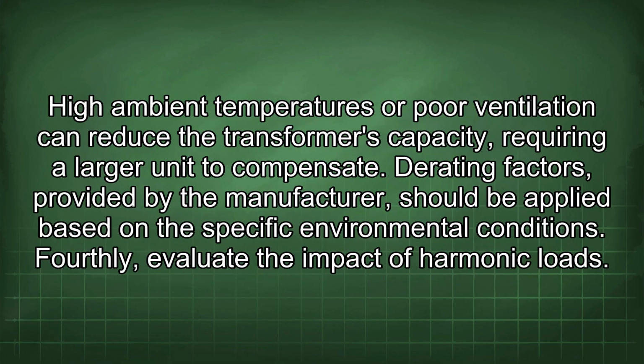High ambient temperatures or poor ventilation can reduce the transformer's capacity, requiring a larger unit to compensate. Derating factors provided by the manufacturer should be applied based on the specific environmental conditions. Fourthly, evaluate the impact of harmonic loads.